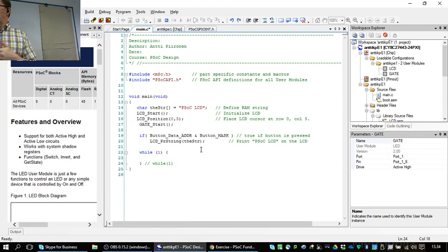I'll show you how to actually do things. Since this is the main execution loop, what should be done there is the execution. Most of the code should be called from that loop, and then the interrupt should be as short as possible. But that's tomorrow's topic. What else?